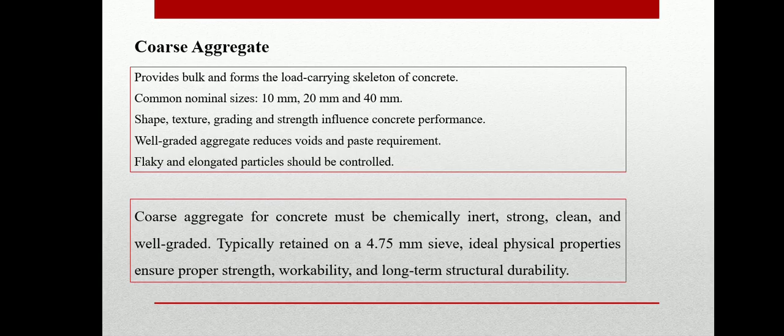The shape, surface texture, the grading, and the inherent strength of the aggregate particles influence the performance of the concrete. A well-graded aggregate, meaning a good mix of different particle sizes, reduces the void content, which in turn reduces how much cement paste we need to fill those voids. It is efficient and it is economical.